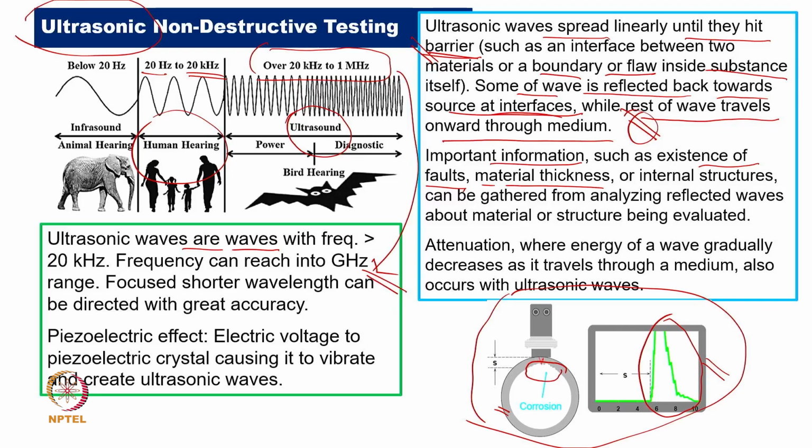However, most of the sensors which come are calibrated and given directly in dimensions. So, the person, or even the company or factory which makes a sensor, needs to have complete knowledge. And I have realized that if you do not use a sensor for a couple of months, when you want to reuse it you again require a recalibration, or time-to-time recalibration is required.